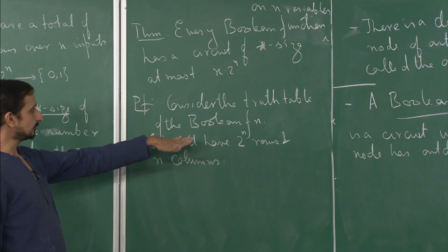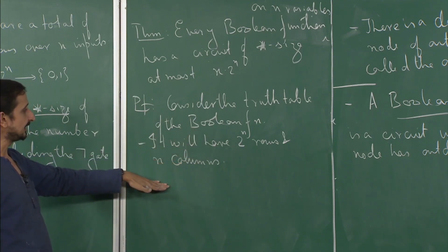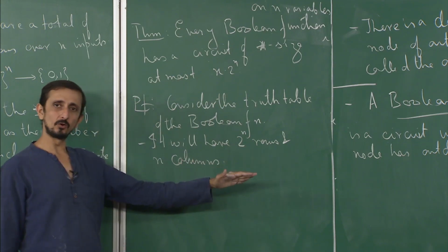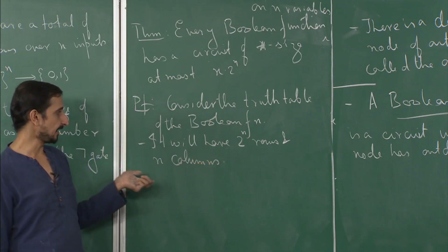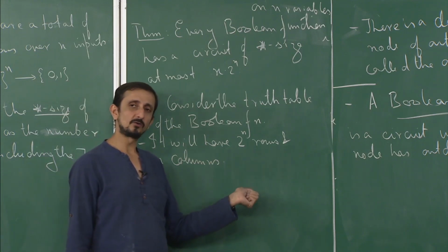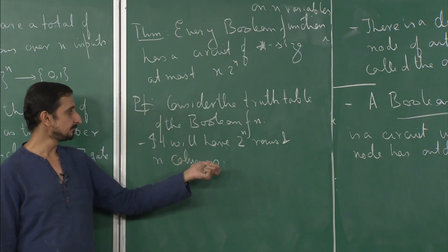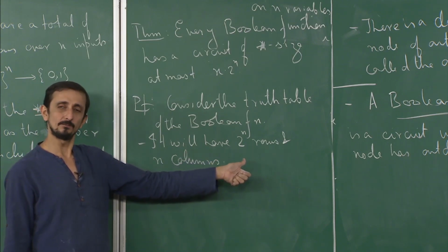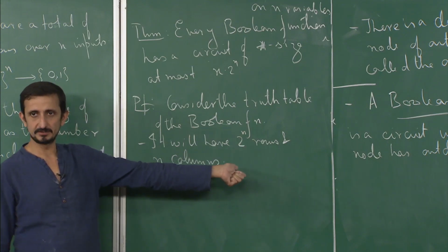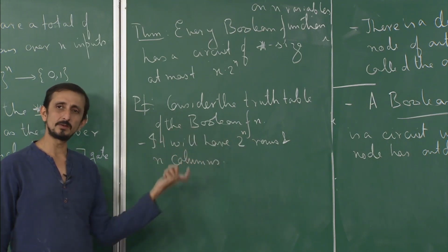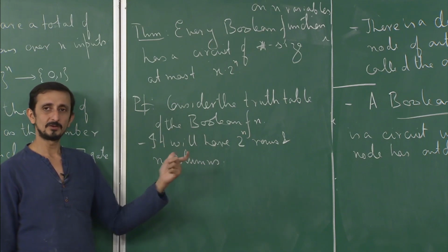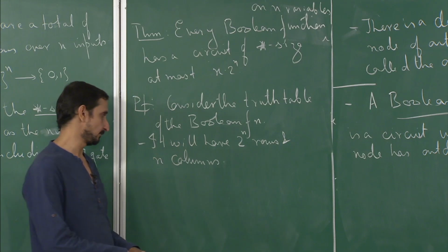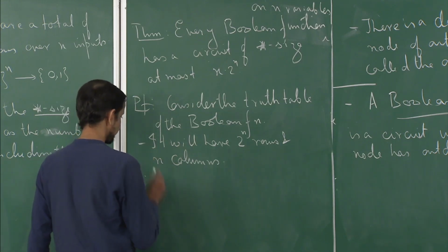Now the value of the function can be thought of as taking an OR of all the rows, and inside a row, it is basically taking an AND of all the what are known as literals. So if a variable is set to 1 in a particular row, you take that variable in its positive form, and if a variable is set to 0 in a particular row of the truth table, you take the negation of that variable, so not of that variable. Okay, so therefore